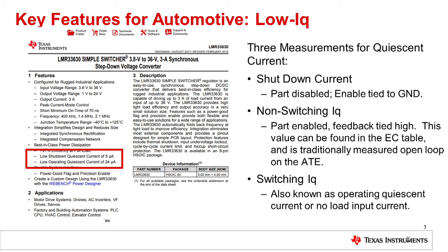The third kind is switching IQ. Switching IQ is also known as operating quiescent current or no load input current, and this is the IQ that you would see within your system design.